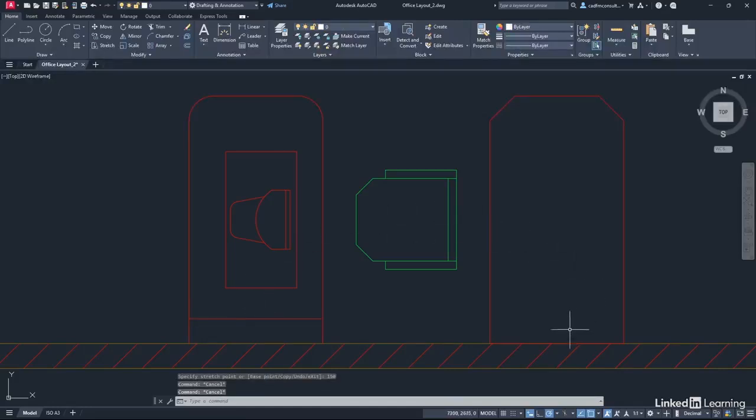Over here to the other desk. Hover, there's the line, left click, click on that center grip, and again drag vertically up the polar tracking line, type in 150 and enter. Now what you've done there is you've moved that line segment from the exploded polyline upwards. Hit escape just to deselect any lines.